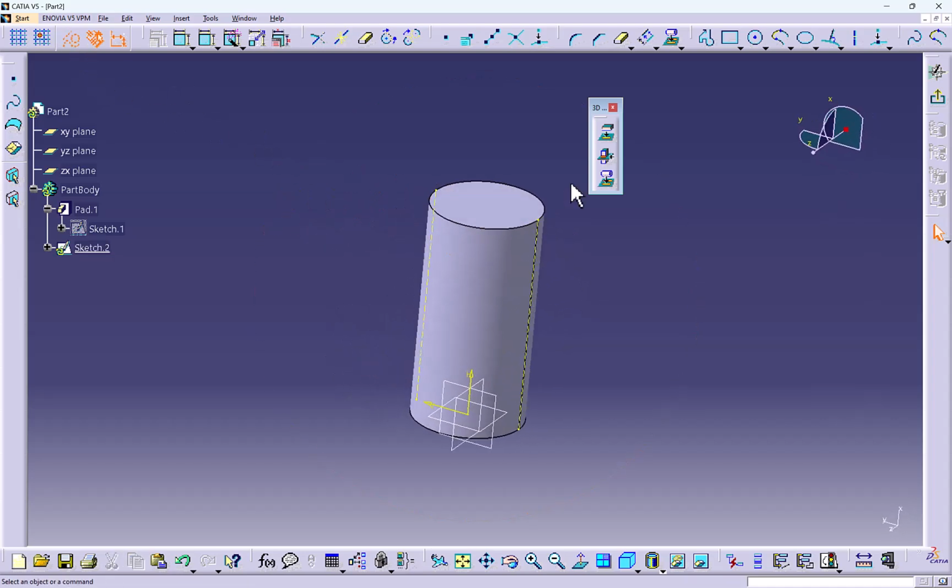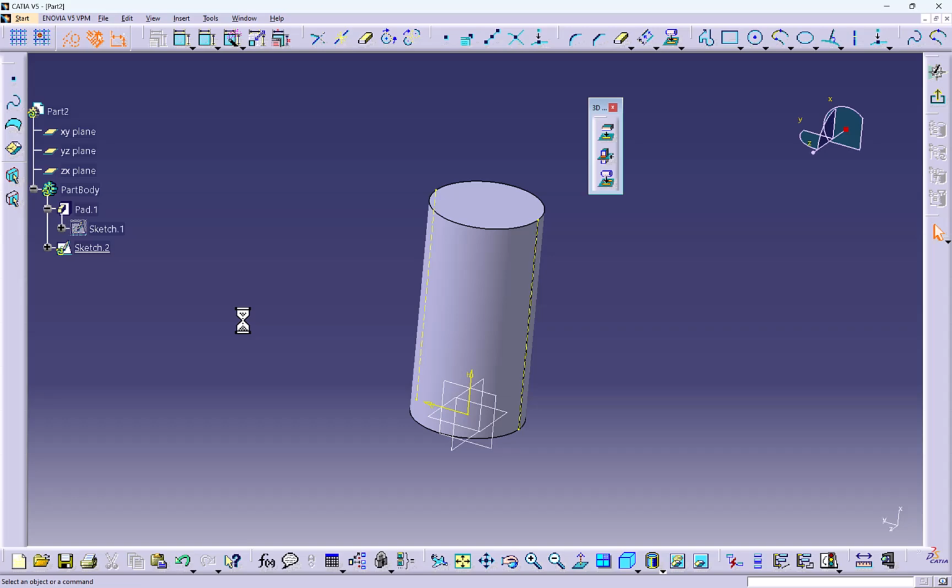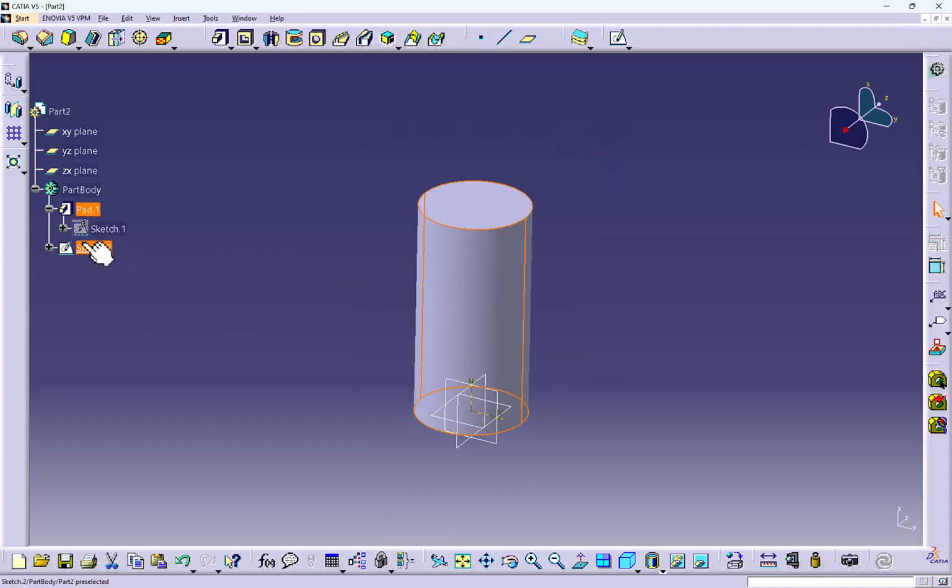Now next, if you have two elements which are intersecting and you want to obtain the intersection curve of the two parts, we can use this method. Let me do one thing. I'll create something to intersect the part body. Let me delete this part. So we'll update it, Control U first, or exit first. Now we can delete all this.